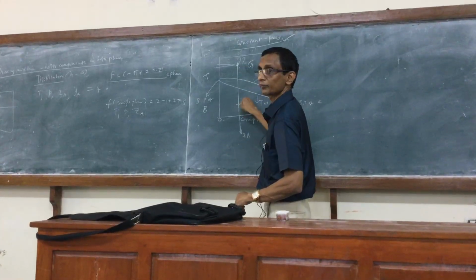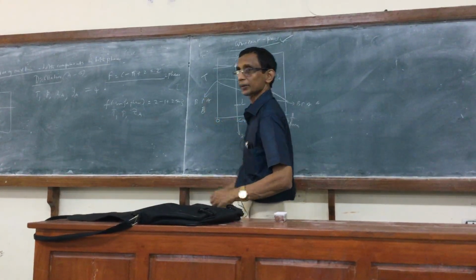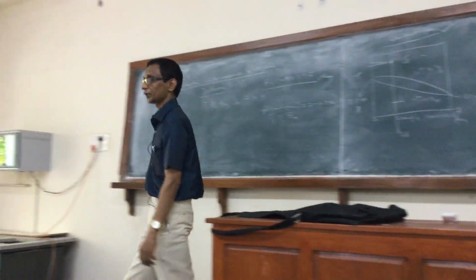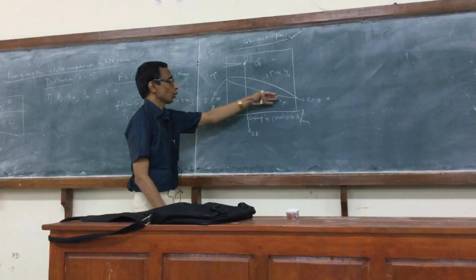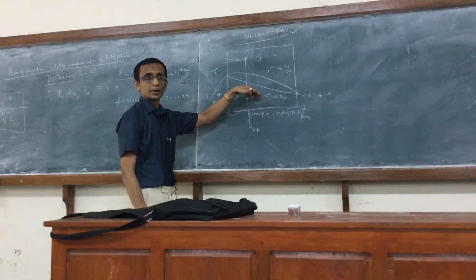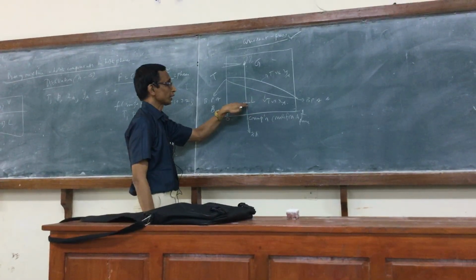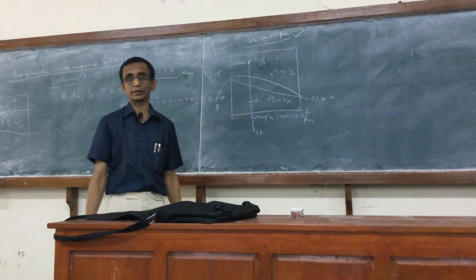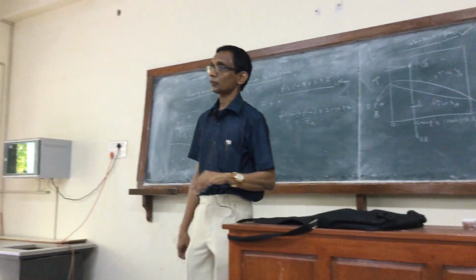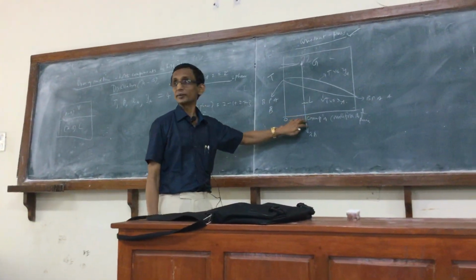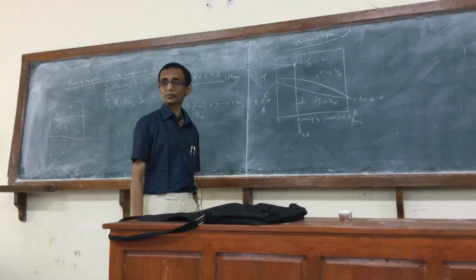Similarly here, I'm calling it Z because it can be either in the gas region or in the liquid. Similarly here, in this whole region, below the T versus XA curve, I need 3 variables to fix the state. Pressure is already chosen. I need 2 extra variables. So they would have to be the temperature as well as the mole fraction. Okay? So that is a single phase.